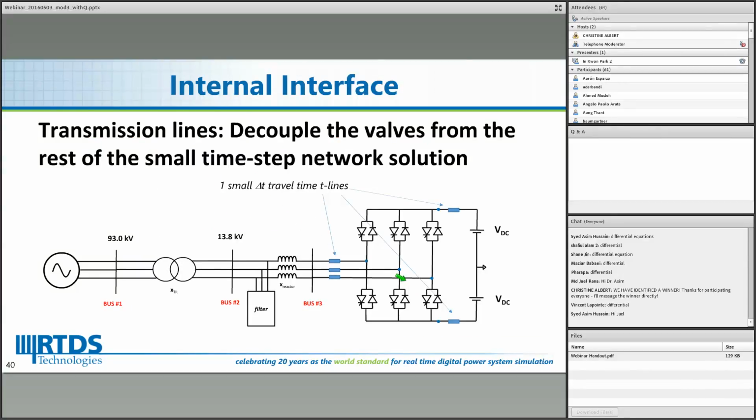That's not the only point where you would find the transmission line. In a single circuit like this, we will still find the small time step transmission line models. Here, the two-level bridge is represented by the low-loss bridge model, or in other words, this part of the circuit is represented by true G matrix switching. Then the rest of the circuit is still based on the conventional way of modeling, which is the constant G matrix approach.